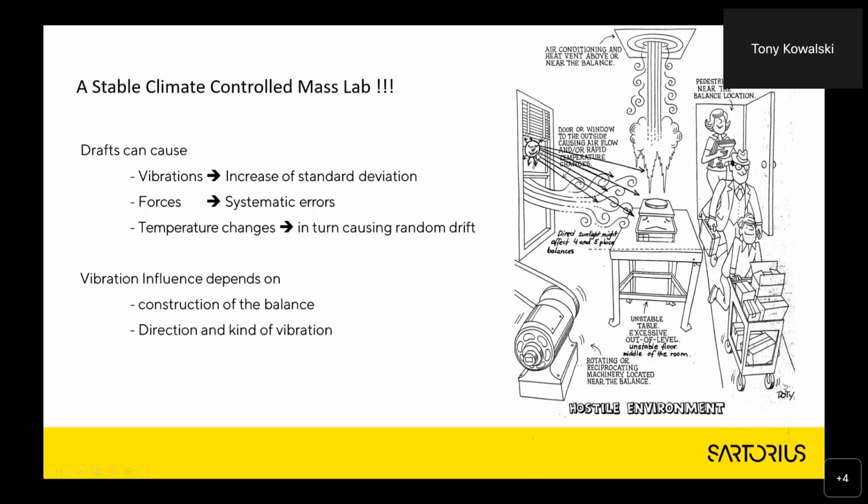Ideal would be to have no windows in the lab, because the sun shining through the window will change the temperature within the laboratory very quickly. And we certainly don't want a lot of people walking through and opening and closing the door, because that will again allow temperature changes and vibrations. There are some really great stone tables now. You can either build your own or you can purchase. Ideal would be if the floor in the lab was separate from a small plinth of maybe concrete that this table can stand upon.